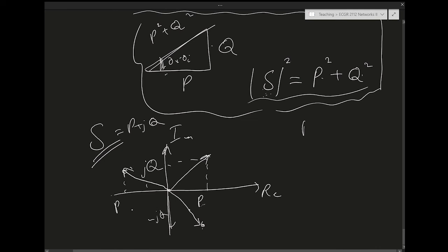It could absorb real power. So the supply could act like a charging battery. Batteries are being charged. It could absorb real power or average power from outside itself and supply reactive power, or it could absorb both. Sorry, this is when P is negative, it's absorbing. So it could also absorb real power and reactive power, so it could live in this quadrant.